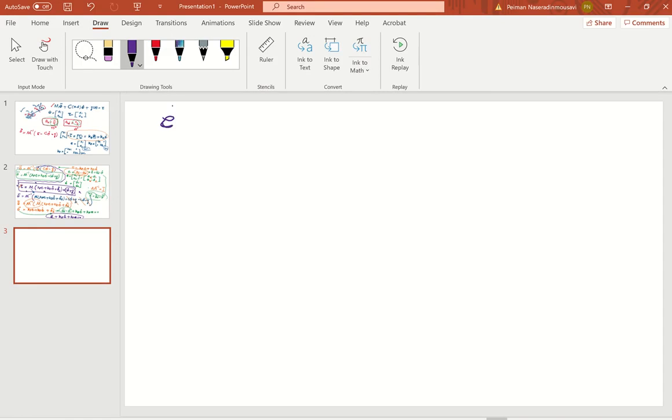So see, this is how we tune the PD coefficients. This is Kd e dot plus Kp e equals 0, because they are decoupled. And this is a diagonal matrix, so we can decouple them. So now, suppose this is a scalar equation.